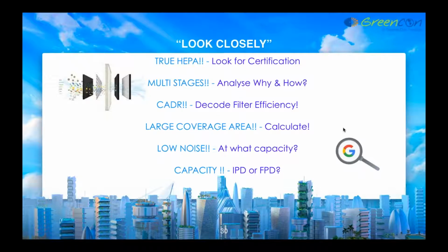So next time when you come across any kind of filtration technology, please look closely and understand what true HEPA means. Look for the certification. Look for what level of staging they are providing. Are they also putting an ESP or an ionizer with HEPA? Why do they need it? Because all those things would actually be utilized to withhold the particles.